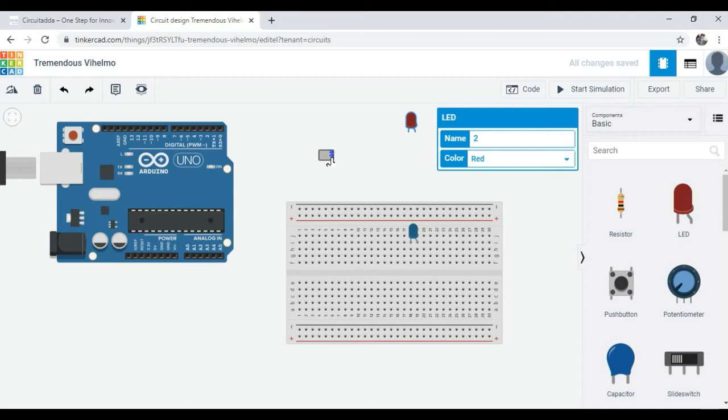That means whenever you purchase an LED, one of the pins will be long and the other will be short. The pin that is longer is the anode, and the pin that is shorter is the cathode, right? Or if a pin has a bend on it, that will definitely represent your anode pin, and the other one will be your cathode pin, right?